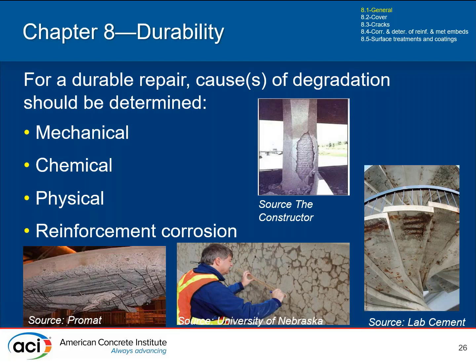What is damaging our structure? As I mentioned, in some ways it's really easy to figure out. We have a history with the structure that's caused the spall. Well, we know that it's corrosion, so you look for sources of corrosion, de-icing salts, and away you go. We need to avoid that.